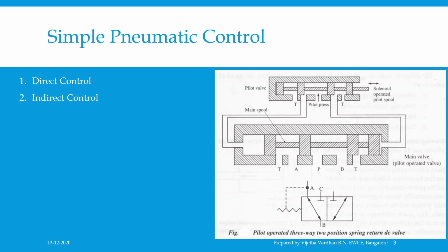Now let us understand the concept of speed control of cylinders. The speed of motion of any cylinder can be controlled by throttling the flow of compressed air either at inlet or at outlet or at both. The degree of speed control available from such simple methods is suitable for a wide range of applications, although actual response time will still vary if the load is variable because of the varying compressibility of air against different loads.